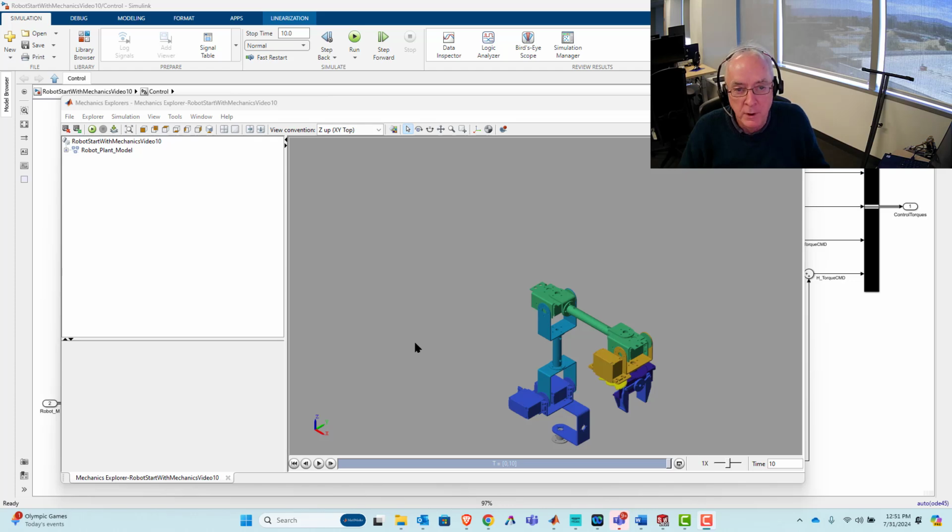Now, what we came up with was a pretty cool trick that we were able to notice that the instability was really forming in the control of the hand, which is really the rotation of this final end effector piece. And so we tuned it up with the PID tuner. It worked beautifully, and we got the whole thing to work.